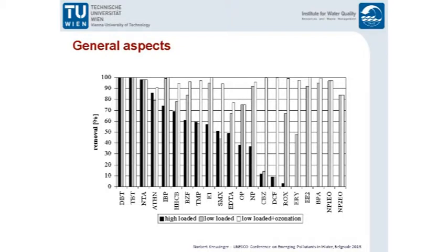What you see here is that we had the opportunity in Vienna, when the wastewater treatment plant was rebuilt from a high-loaded carbon removal plant to a nitrification, denitrification plant, to investigate some micropollutants. You see the black bars show that even that high-loaded treatment plant was able to remove certain substances, usually those with a very high sorption potential, to quite some extent. After the adaptation to the low-loaded nitrification, denitrification plant, you see that more substances are removed. And this is rather on the right side.